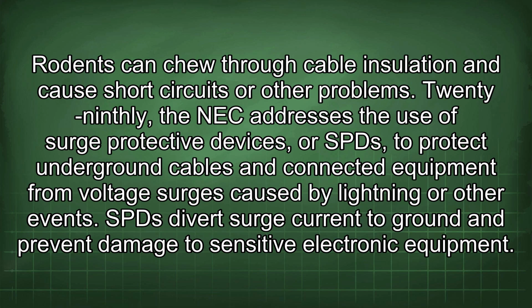29thly, the NEC addresses the use of surge protective devices, or SPDs, to protect underground cables and connected equipment from voltage surges caused by lightning or other events. SPDs divert surge current to ground and prevent damage to sensitive electronic equipment.